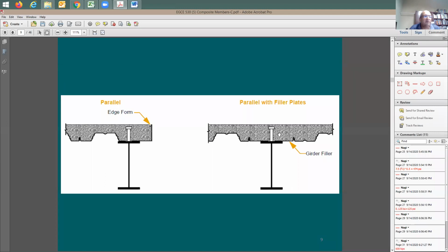If you need to transfer to the other side of the section, it's going to be moving from the steel section to the concrete as shear in the mechanical connectors. So this mechanical connector is not going to be seeing tension force, and instead is going to be seeing shear force.